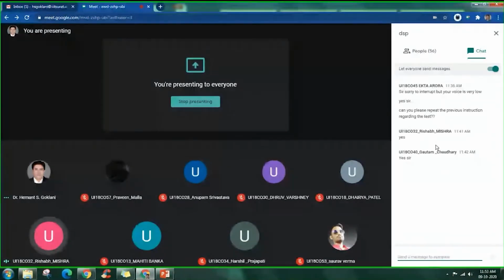Yeah, Rishabh. So the exact answer is, when we say linear system, it means it fulfills two requirements. It will fulfill the property of additivity or superposition, and it will fulfill the property of homogeneity. So if I apply x1(n) and x2(n) separately, and whatever outputs I get, y1(n) and y2(n), then if I add the signals x1(n) and x2(n), the output I get must be the same as their combined output. So that property is superposition or the additive property.